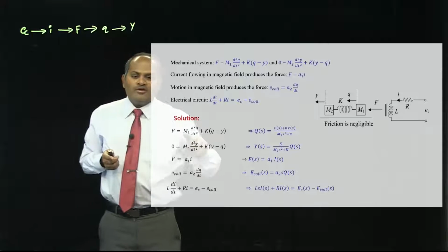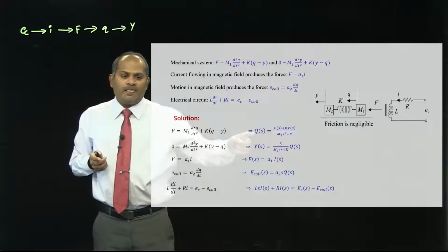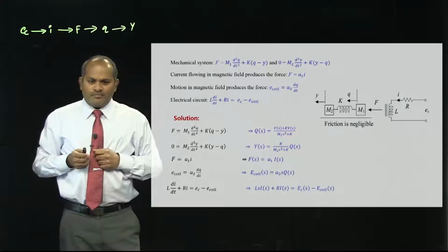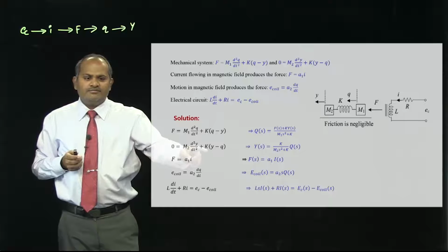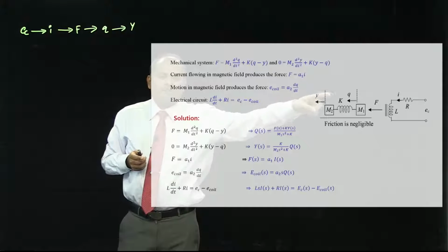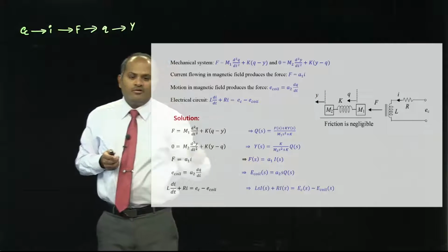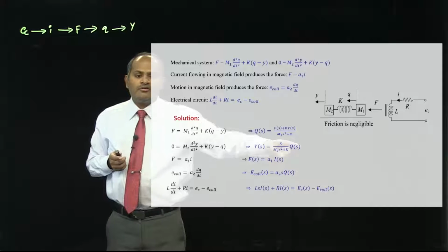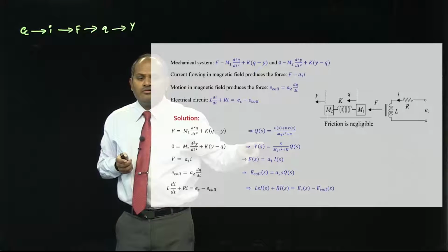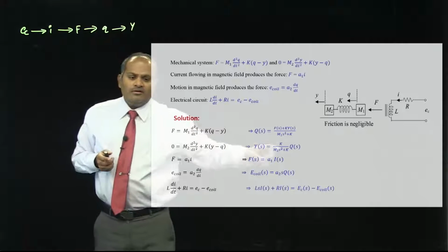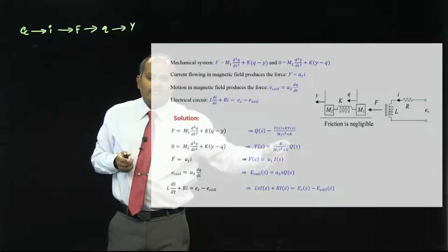So, now once I convert into Laplace transform, I can write in the output form Q of s is equal to F of s plus ky by m s square plus. So, you can write in this form. Now, for the second equation, Q produces Y, right? Q is the input, Y is the output. So, convert into Laplace transform, I can write Y of s is equal to k by s into Q. Always write output is equal to a function, a transfer function, into the input.